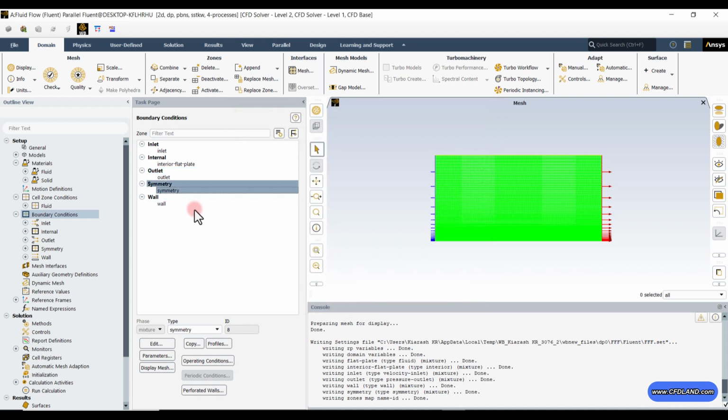Finally, before getting to the wall boundary, you can see that the software automatically uses a symmetry type boundary condition for the symmetry boundary. As you may remember, in Ansys meshing, we defined a symmetry name and called this absolute wall symmetry. This is where it can help. So what is a symmetry boundary? Actually, it acts like a mirror. So the software will consider no normal velocity or normal variable on this plane. So it will actually act like a mirror, and this can reduce the computational cost.